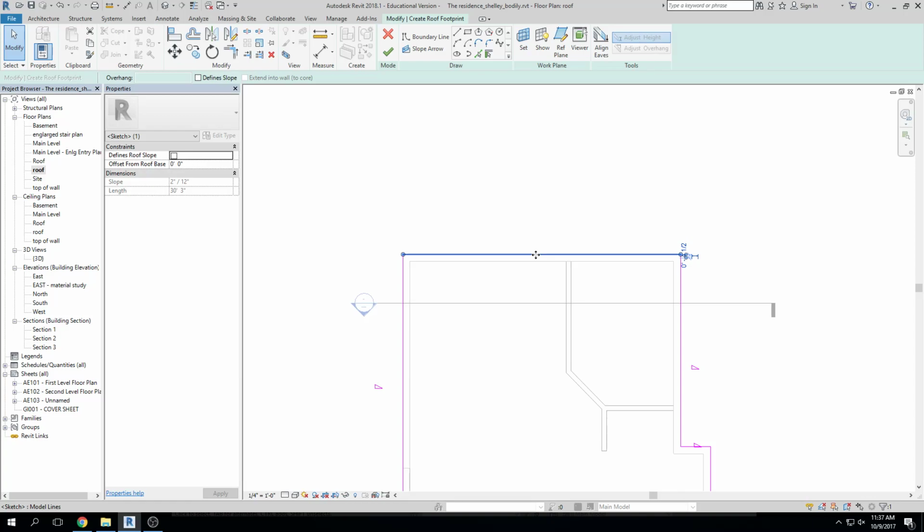So here's the ridge line, this and this. If we give that a 0 slope, that will indicate a gable. So it'll just be flat. Does that make sense? So we would give this line a slope. It would slope up to there. It would slope up to there. It's sloping up to there. It's sloping up to there, right? And then this 0 slope, it's flat on the end. So we get that gable, okay?